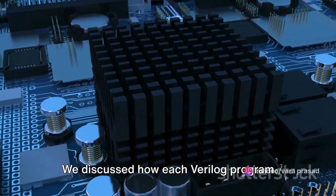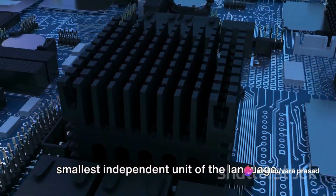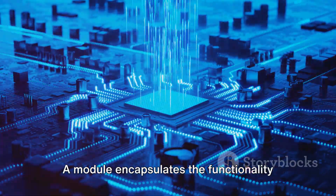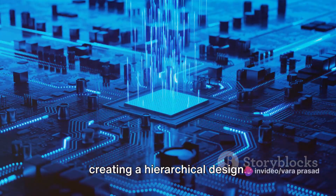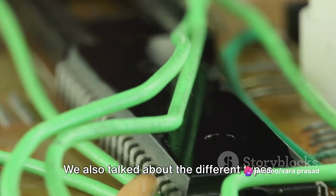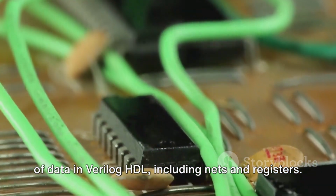We discussed how each Verilog program consists of a module, which is the smallest independent unit of the language. A module encapsulates the functionality of a digital systems component, and these modules can be instanced in other modules, creating a hierarchical design.